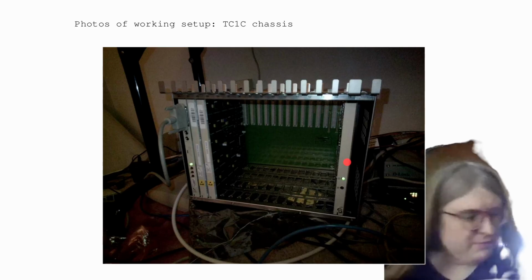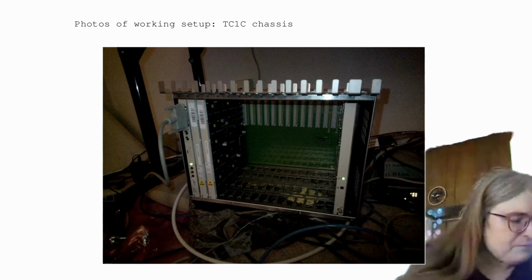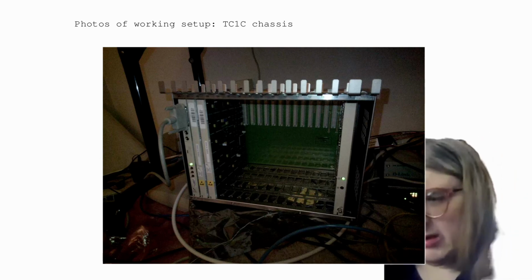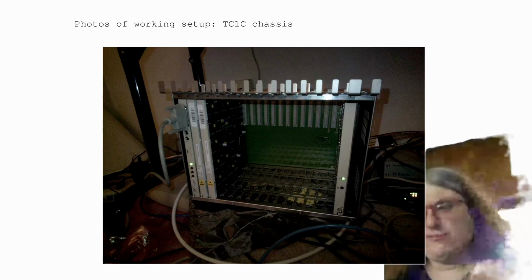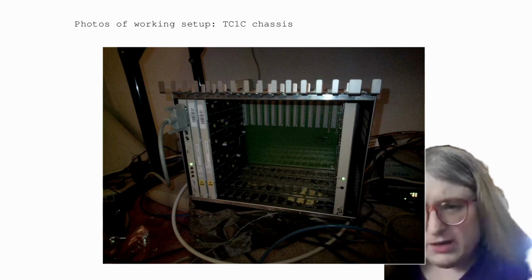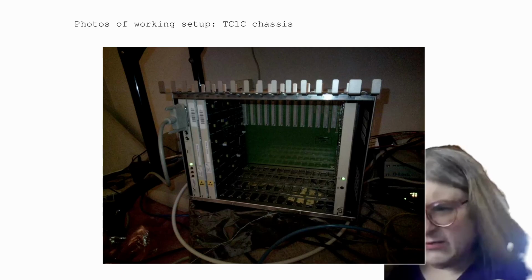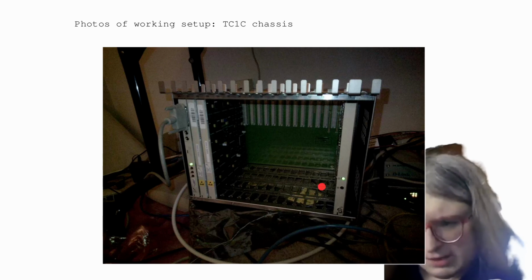So this is the power supply module. You've got 48-volt DC power coming in the back. That's just your typical telco equipment, so 48-volt DC, positive grounded, so it's really minus 48-volt DC. It comes into this power supply module. There's a little switch on the bottom that you can turn it on and off. This power supply module takes in 48 volts and puts out a positive 5 and negative 5. I wonder what they use negative 5 for, but it puts out both positive and negative 5.